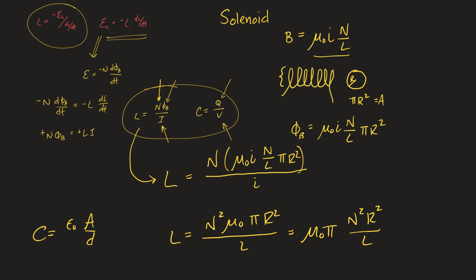I find that to be a little bit weird because we tend to think of other things being more effective. A resistor, if you have more of that material, it does more to resist the flow of charged particles. But we have a similar kind of thing with a capacitor, but I think it makes more realistic sense. If I get the plates closer together, I get more capacitance. But this is saying if I make my loops all packed closer together, I get better inductance. And this is probably because it's concentrating the flux in one place. And the more the flux is concentrated, the more inductance, more back EMF you get.